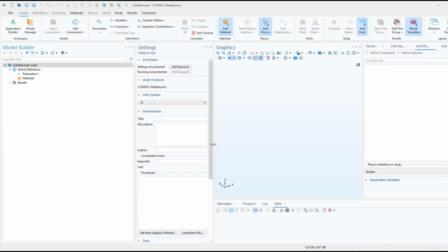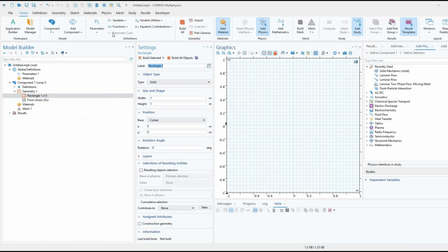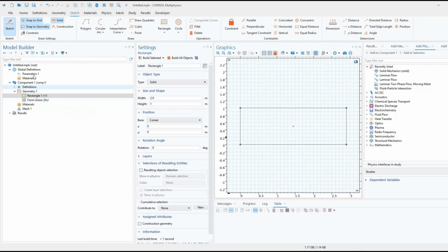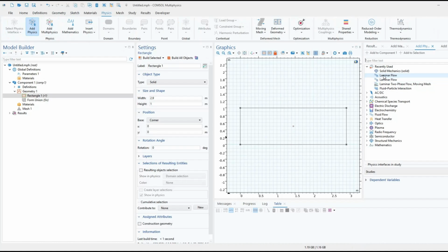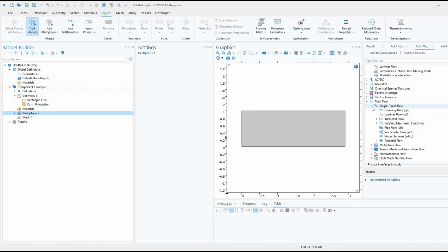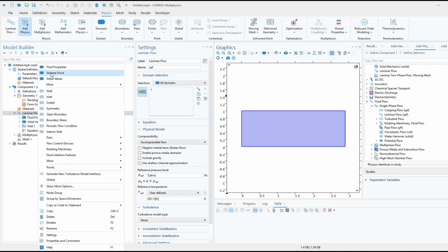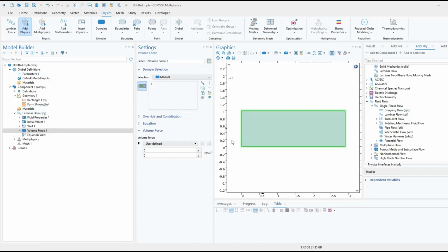Let's take an example we talked about, wave propagation. Suppose I want to model a wave traveling inside a 2D fluid domain. First, I define a geometry. Maybe it's something simple, a rectangle. Then I choose a physics interface. That's a fluid flow. Now I apply a boundary condition, which is like the exciting force for the domain. Maybe I prescribe a sinusoidal excitation at the boundary. That sine wave has a frequency and it has an amplitude and a phase.